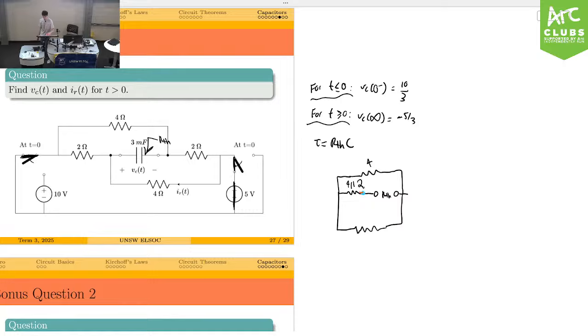Now, why does that make sense? Well, this circuit is symmetric. If I flip this vertically, it's the same thing. So logically, it will be the same parallel network. So you've got 2 pairs of 4 parallel 2, and then when you simplify them, they're just in series after that. So RTH will equal 4 parallel 2 plus 4 parallel 2. Are there any questions about why that's correct?